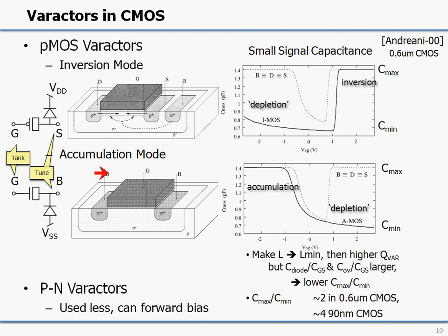In practice, when you use those varactors, you're going to see that the parasitics matter, and there are quite a few parasitics on the source side. So typically, you're going to take the gate side and attach that to the tank, whereas you keep the source side to attach the tune node to it, because it will load the tank much less at that point.